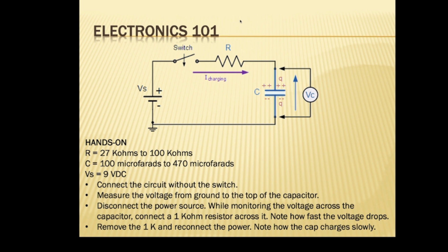There we go. Now take your meter and measure across the capacitor. What value is your capacitor? I don't know, I think it's pretty high. How do I do this? Just go to DC volts. There we go. Measure across the capacitor from here. It doesn't matter, negative or positive. On this meter, it doesn't matter. It'll automatically adjust.